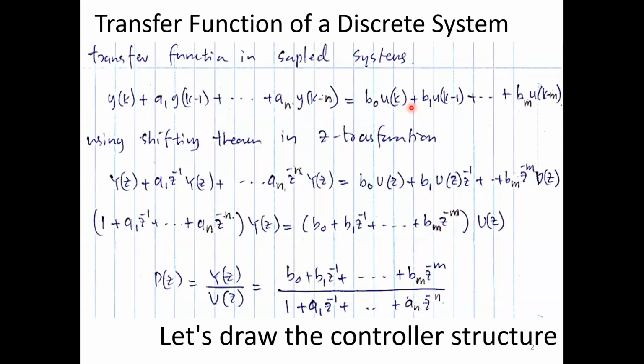So in discrete time, you can avoid that word time altogether and stick to index, time index. First sample, second sample, third, fourth, and so on. So the time in between two consecutive signals is called the sampling interval, right? And you can record it somewhere and just keep it there. You don't have to bring it into the equation, okay? You use sampling interval in the process, and at some point, you remove that from the equation and stick only to the index, K, okay?